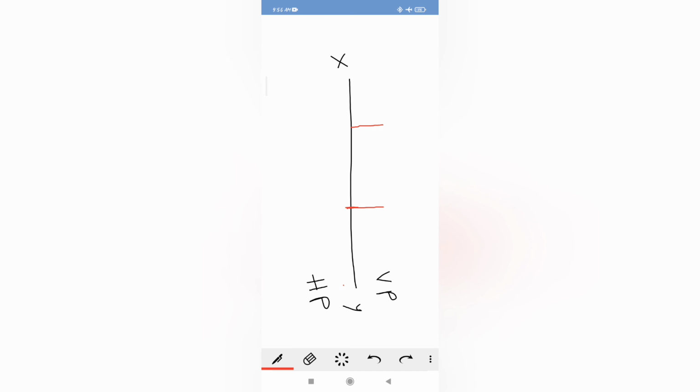of 30 mm, this must be thin, that's why I am representing A dash B1 dash. This is AB1 because the point B's position keeps on changing. That's why I have represented it with B1 fake, as this is a fake view. As the point A's position remains constant, it is represented with A and A dash.